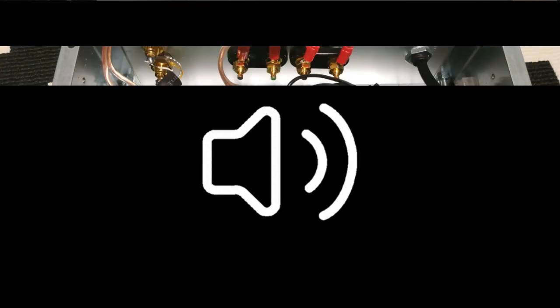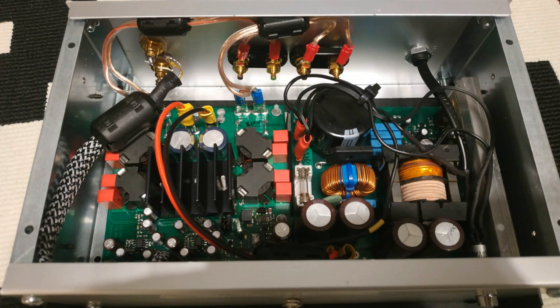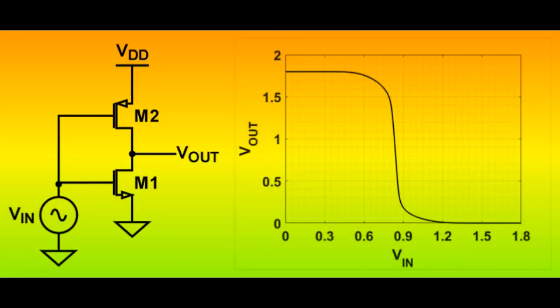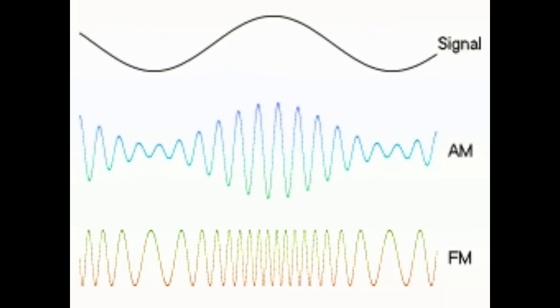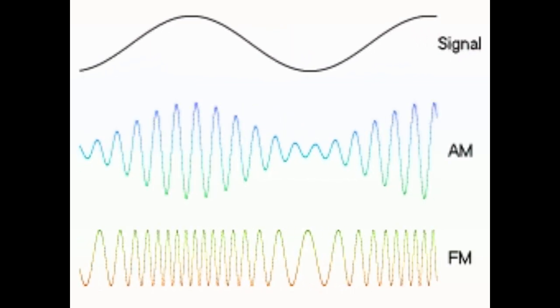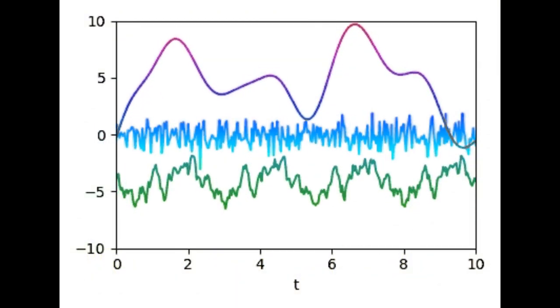We can define the characteristics of an ideal amplifier from the previous discussion in terms of gain, meaning voltage gain. The gain of the amplifier, A, must be constant for different values of the input signal. Gain should not be affected by frequency. All signals with different frequencies should be amplified by the same amount.